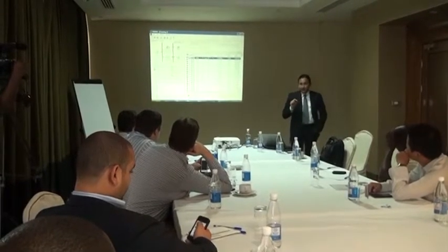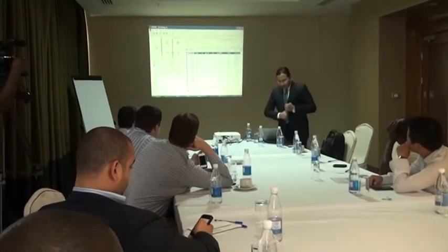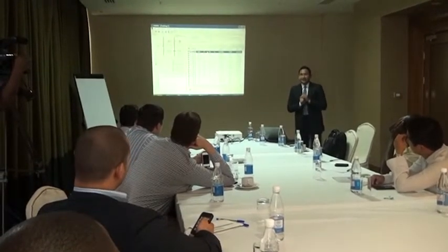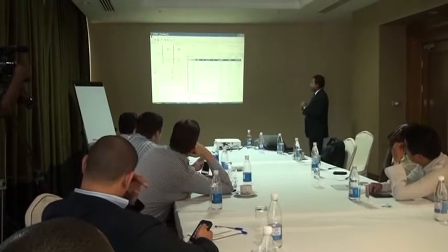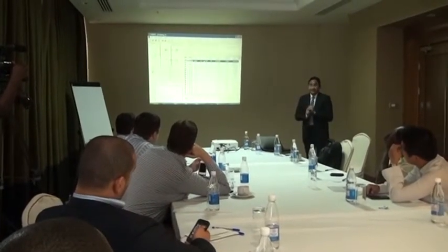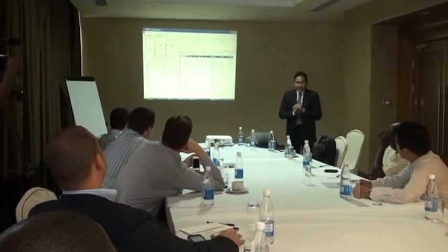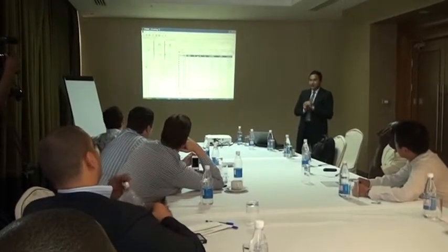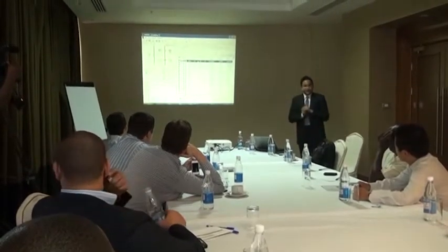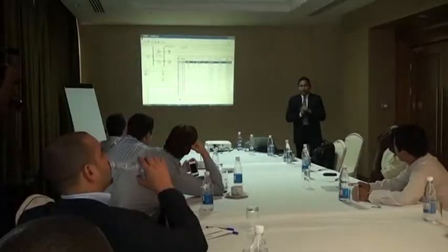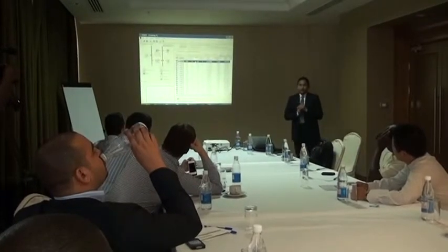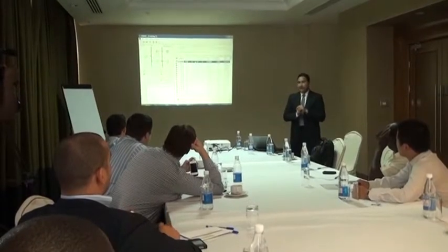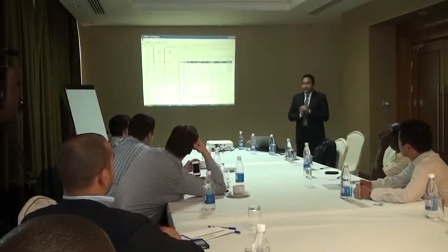Once you double click, I will show you another criterion to look at while selecting the right solution. It is a logistics-related area, not technical: the land availability. HOMER is suggesting 6 kilowatt is the best solution. But is it the best solution if you don't have the land? No. For 6 kilowatt, you need about 24 pieces of PVs, which will need about 35 to 40 square meters of land. Do you have enough land available? Do you have any land without shading? These are the things you have to look at practically.